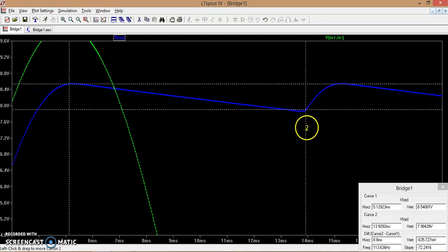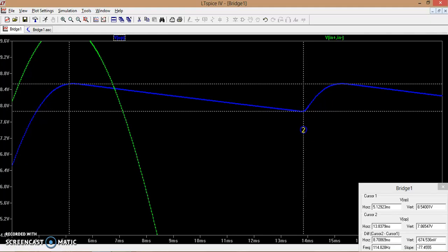Now you can see you can slightly adjust it to the peak value. Now the difference of those two is 674 millivolts. So that's what is ripple voltage. You can certainly verify this by calculating from the theoretical equation, where the ripple voltage for a full wave rectifier happens to be (Vp minus 2Vd) by 2Frs. So this way you can get a rectified waveform.